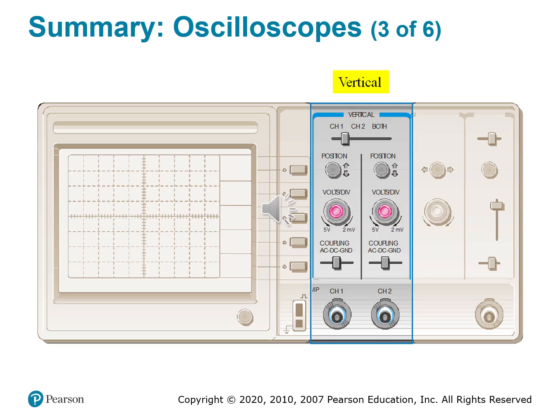Then let's move on to the coupling switch: AC, DC, and ground. AC coupling blocks the DC component and shows only the AC part of the waveform. Perfect for audio or ripple measurements, right? DC coupling shows the entire waveform, including that DC offset. And then we have ground, which of course disconnects the signal entirely and sets a flat line at the ground reference. So this is helpful for zeroing out the vertical position.